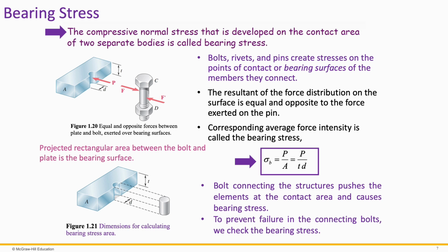Take a look at figure 120. Here we see a bolt inserted through a plate. When the force F is applied to the bolt, it presses against the inner surface of the hole in the plate. At the same time, by Newton's third law, the plate pushes back on the bolt with an equal and opposite force. The contact area between the bolt and the inner wall of the hole is where the bearing stress develops. Now please look at figure 121.